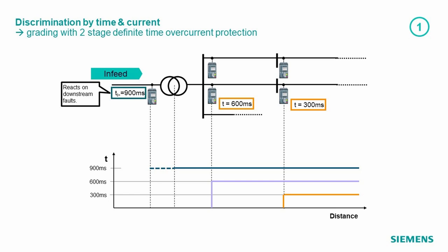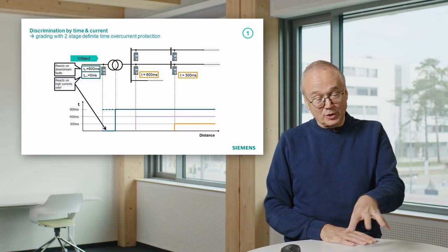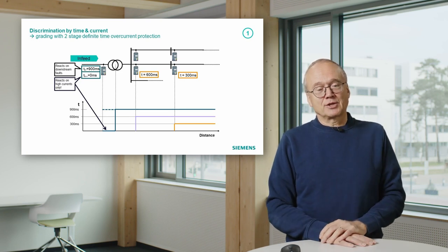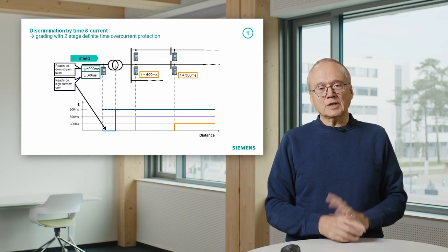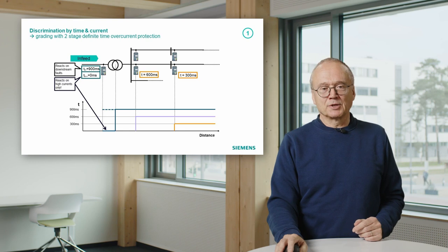It must be a short circuit on the high voltage side, and there is no need for a long time delay, and then it can trip faults on the high voltage side of a transformer without time delay. That means we must do short circuit calculations for the system and then make the timer setting in an adjusted way. That is a thing that you often find in connection with transformers.